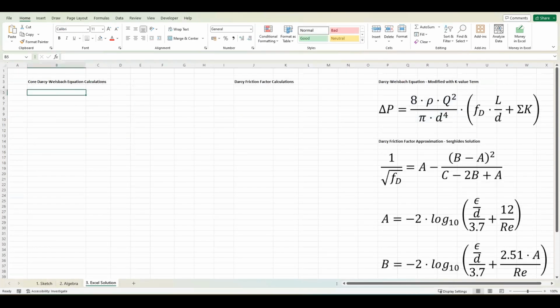So what we're going to do is start with some of the key parameters that we need to think about. The way we're going to build it is we're going to take into account static head, obviously, and source pressure. The source pressure is essentially the discharge pressure of the pump. So we're going to say discharge pressure, P pump, and we're going to express this in bar gauge. Let's say as our first initial guess, it's 1 bar gauge.